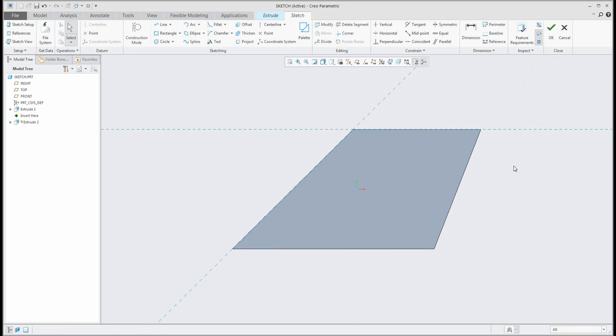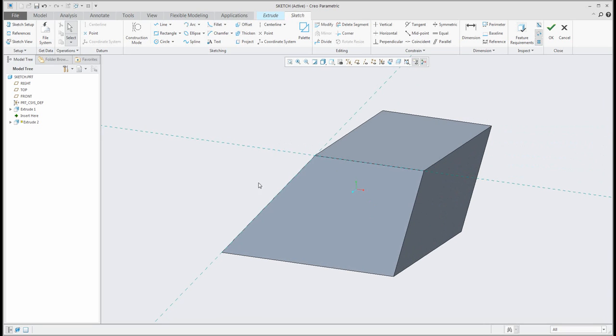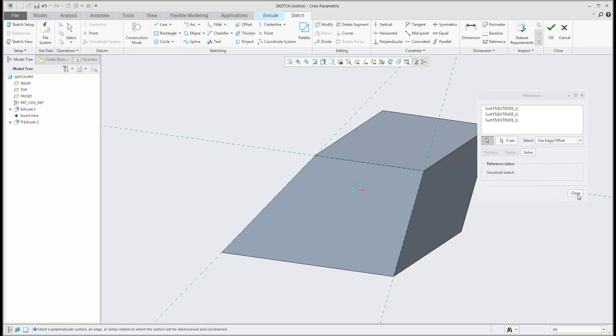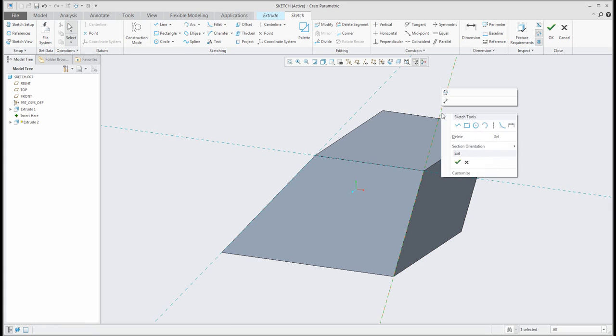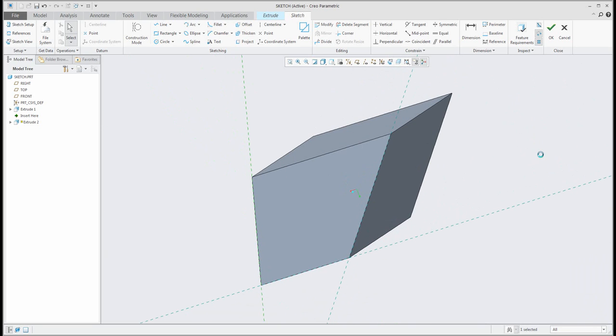Yeah? So the system doesn't care what you have specified in Sketch Setup, because you have specified the modification of the orientation directly in the sketch. So right now you know how to orient the model directly, for example, for the Sketch Setup, or base it on the references. If you add another reference, for example this one, again you can spin and orient like you need, for example vertical. Yeah.